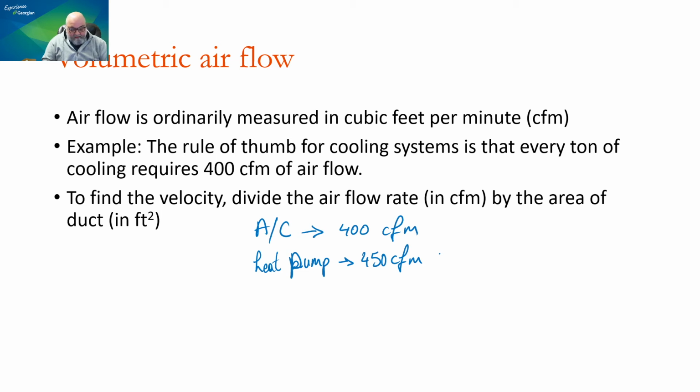Okay. Now, what we need to work on in addition to the pressure is the flow rate. All right. Yes, we need to do the flow rate, but there is one more thing we need to do, and that is finding the velocity of the airflow. It's called airflow rate. Okay. So the velocity, why is it important to know the velocity of the airflow? Because of comfort in terms of feeling a cold draft, for example, or because of the noise.